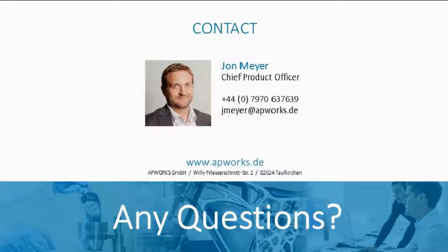I've seen some interesting examples of depositing copper onto steel, for example, to improve thermal conductivity. And that's something that if you go and have a look at what the guys making rocket motors with AM out in the US mainly are doing, there are some really interesting applications there. You know, Inconel thrusters with copper exteriors done in 2 steps with machined cooling channels. It's amazing stuff. So it's worth having a search.